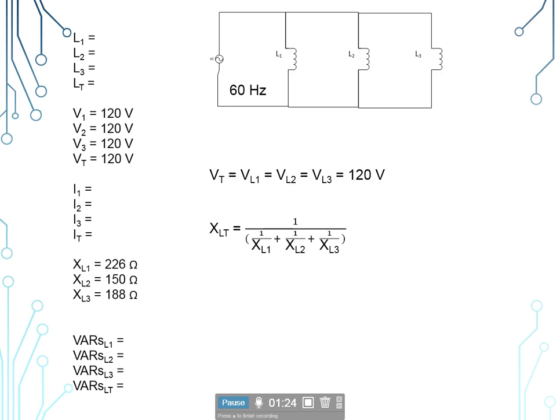Now we need to find our total inductive reactance. And we'll use the reciprocal formula, a little bit of a variation on it. It'll be 1 divided by, open our parenthesis, 1 divided by X sub L1 plus 1 divided by X sub L2 plus 1 divided by X sub L3, close our parenthesis.